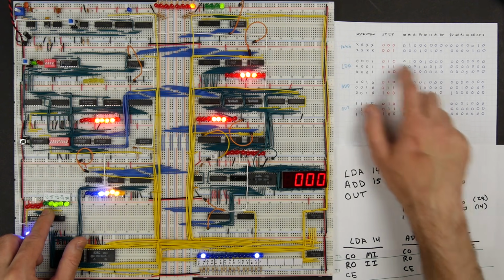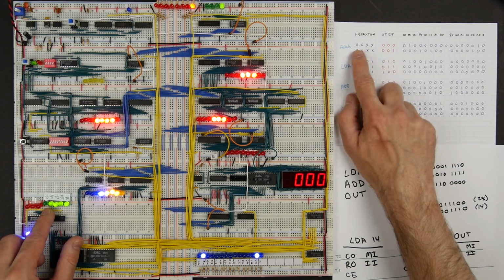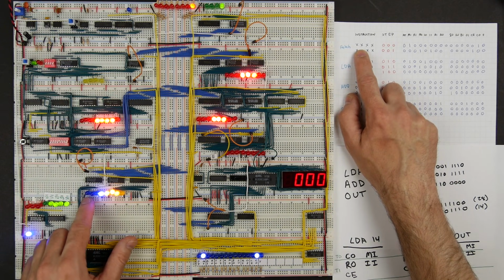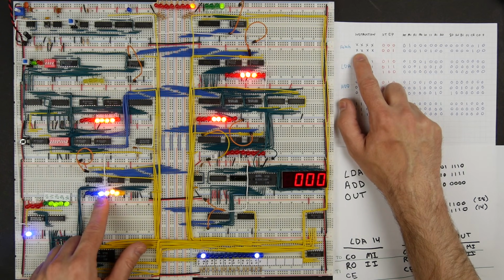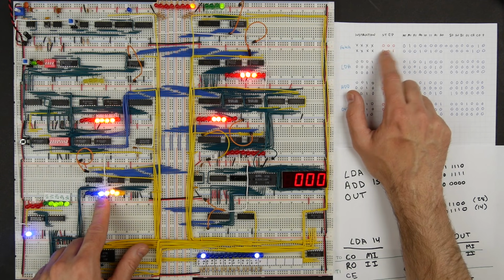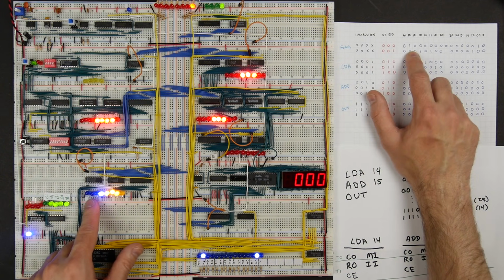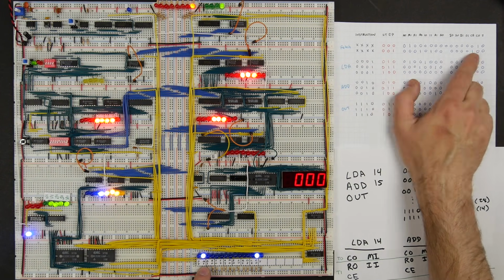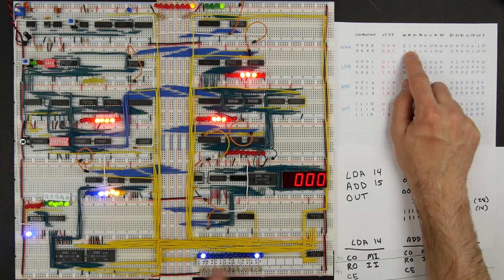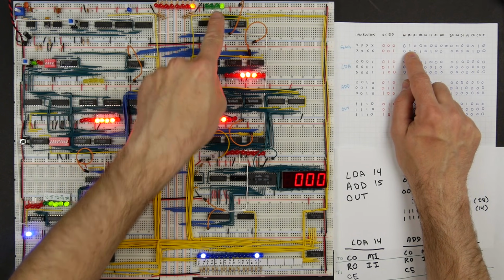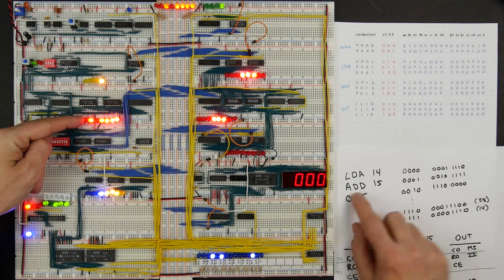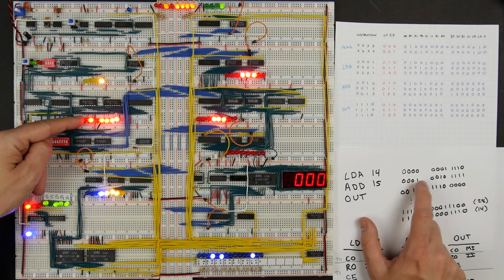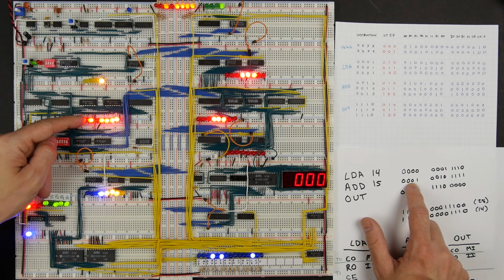And so now we're back at time t0. So we're at step 0. Our instruction is different now, though, right? Before we had instruction 0 in here, which we haven't really defined. Now we have instruction 1, but it doesn't matter, right? Because we programmed this step 0 for every instruction. So we're still going to do the same thing. We're still going to do the counter out and the memory address register in. But now this time the counter is 1. So we're going to put a 1 into the memory address register, which will now get the next instruction, which is add 15. That's what we programmed into address 1.